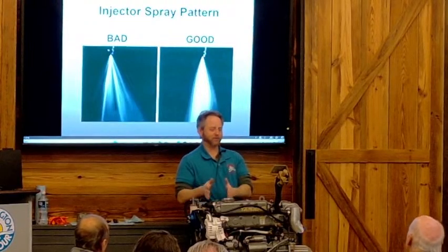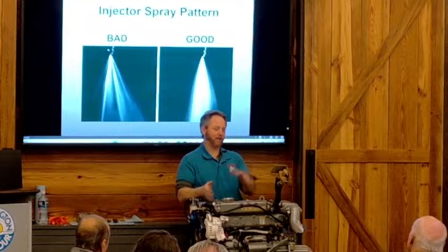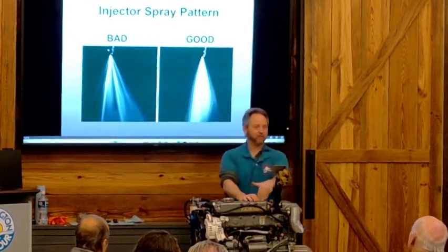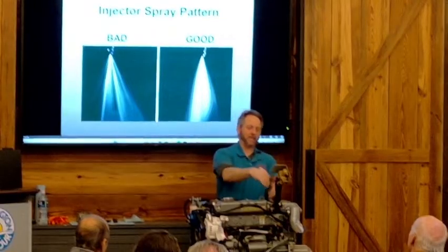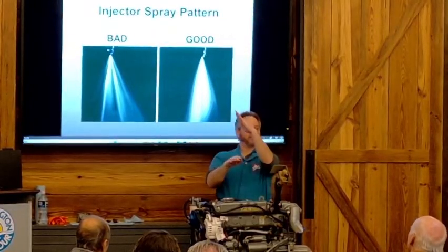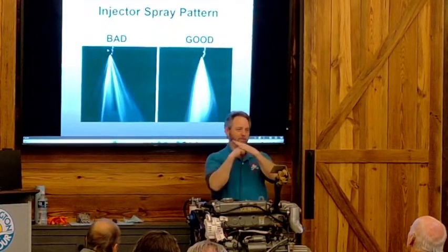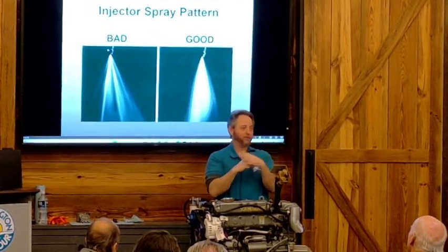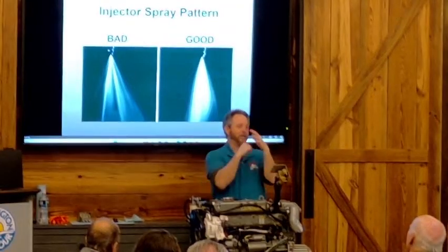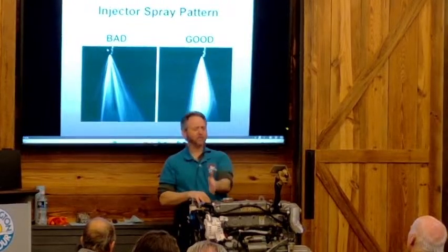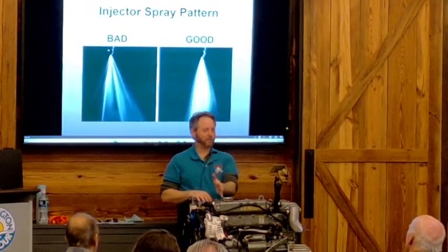That was odd because normally when you see bent connecting rods, it's usually the back cylinder, because if you ever get seawater into your exhaust, it tends to go into that back cylinder since the engine's on an incline, and the water runs that way first. And liquid isn't compressible, so if you get a slug of water on top of the piston while it's moving, something gives. But this was on the front cylinder, which was a little confusing.